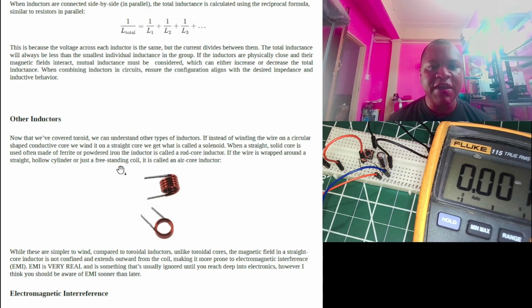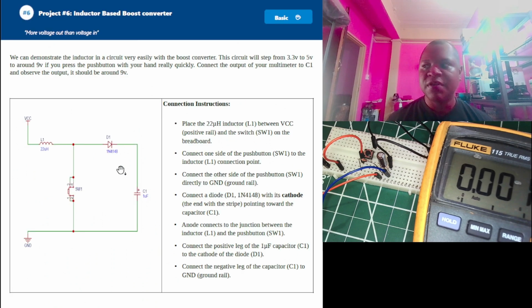In this guide I went through a lot of stuff, but I really want to show you how we actually use these inductors. So I have this circuit set up here, and this circuit is a boost converter circuit. You typically see these all over the place. Typically they'll replace the switch here with a microcontroller.